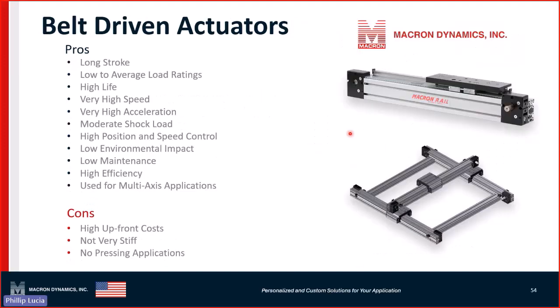Now we get into belt-driven actuators. I'm the representative for Macron, so we have a couple of Macron pictures up here, but basically you have a belt and some pulleys, and you end up putting a motor driving this shaft, and you can move that carriage back and forth. These can actually be compounded to XY, XZ, XYZ, so you can fit the application down to where it needs to go and move in 3 dimensions. The pros of a belt drive: they can go long stroke. We've done hundreds of feet of stroke with a belt drive.